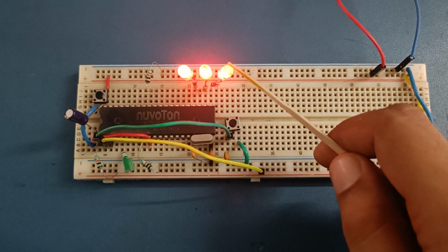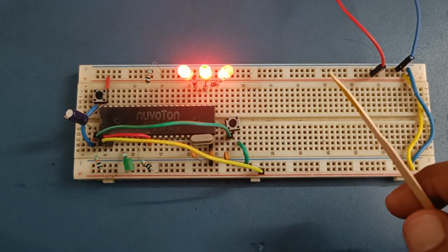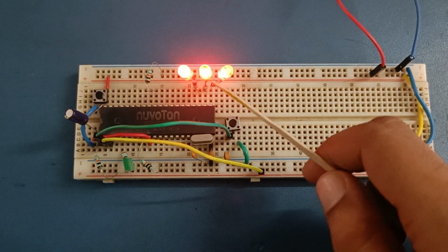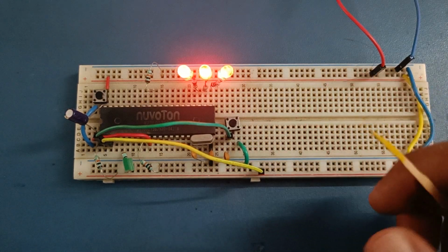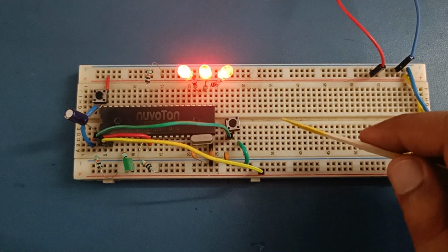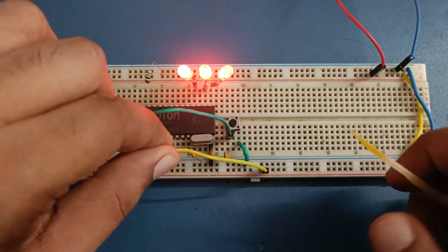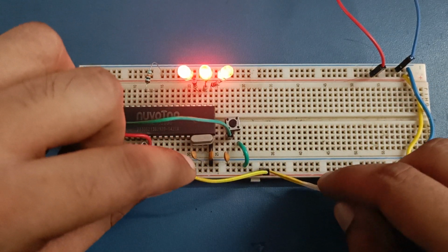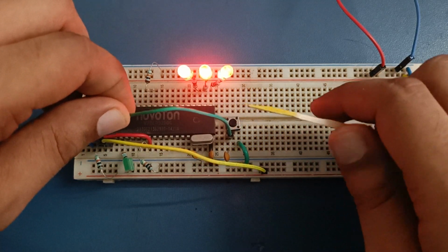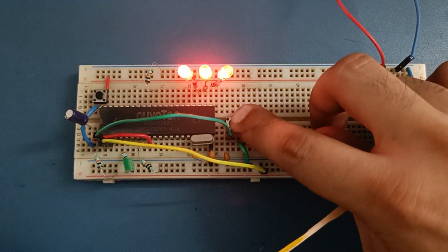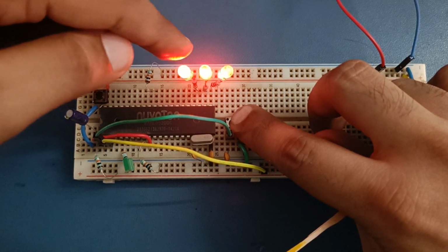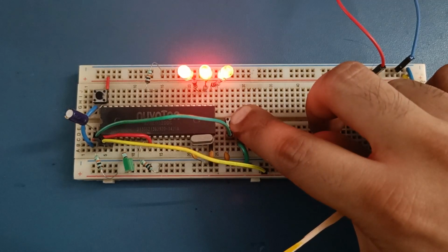This is the LSB. TH2 and TL2 form the 16-bit register, and these are the last 3 bits of that register, as we are using only 3 bits to count from 0 to 7. This is the T2EX pin, which I've connected to 5 volts, so this acts as an up counter. And this is the T2 pin, to which I've connected one button. I'll press this button. It will make the pin low, which will cause the counting registers to increment.